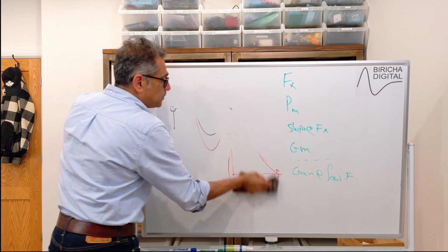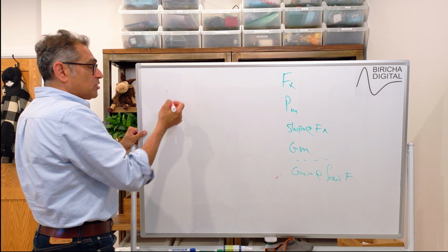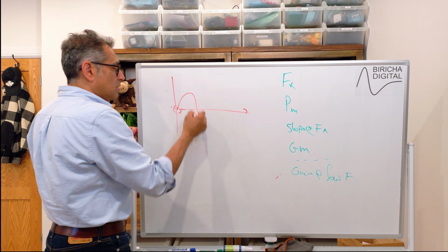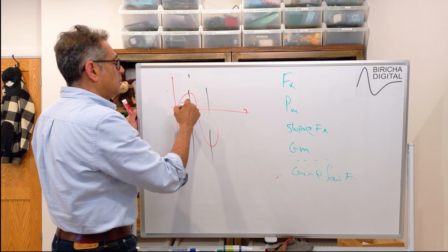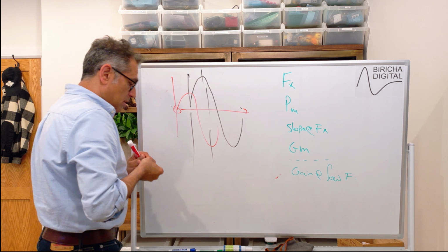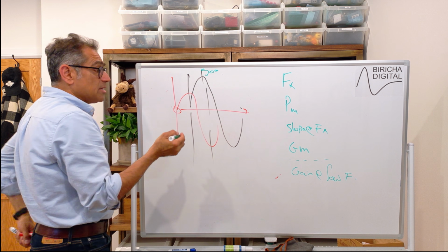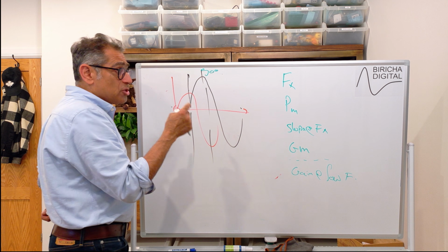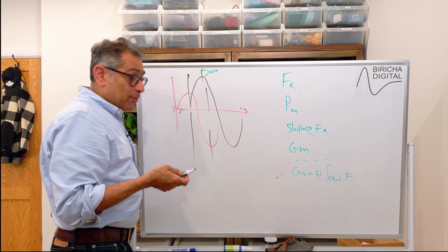So again, let us say that I inject the same 1 volt 10 hertz sine wave, and now in addition to a height change, there is also a phase shift. Again, for simplicity, let's say this is 90 degrees. There's a phase lag of 90 degrees of the sine wave that came out with respect to the sine wave that I injected in. So in addition to knowing that the gain was 2, I now know that there is a phase lag of 90, and of course I will have a second plot.